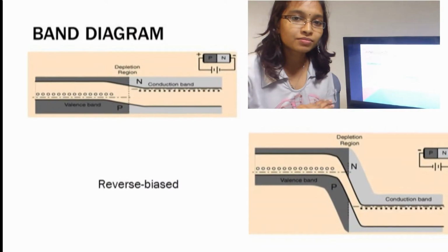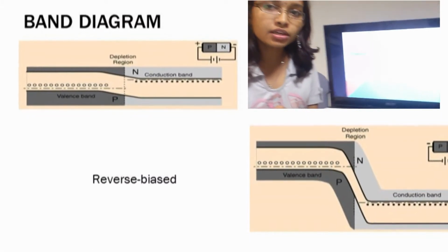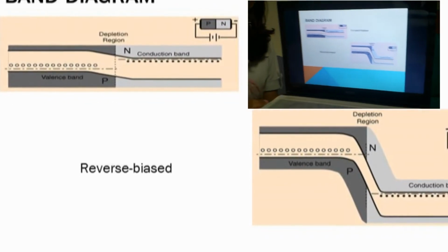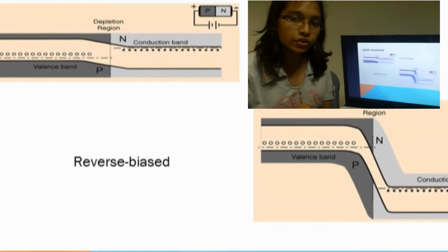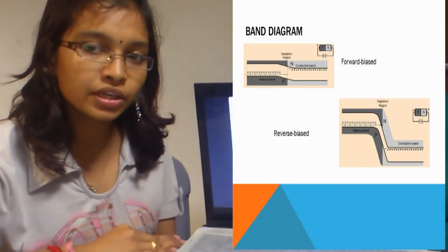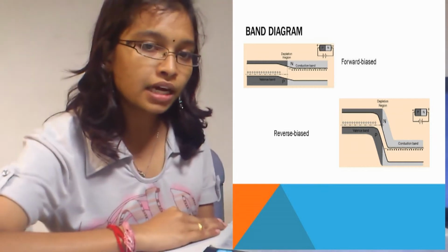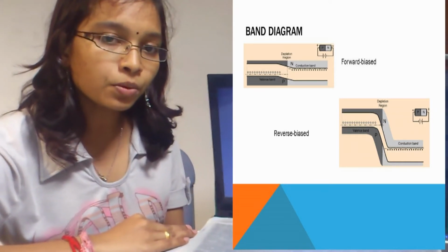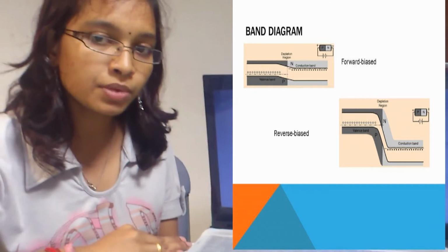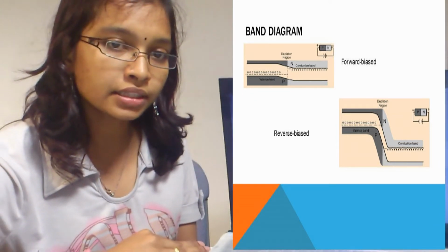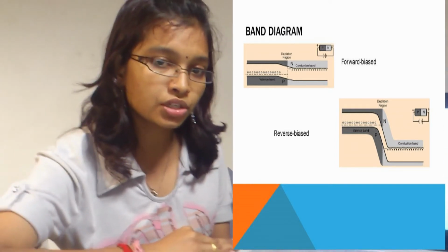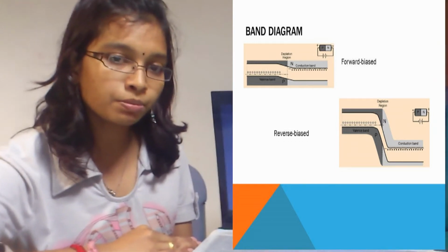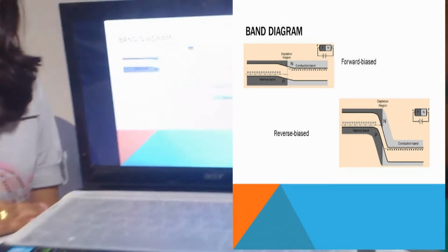To reverse bias the PN junction, the P side is made more negative, making it uphill for electrons moving across the junction. The conduction direction for electrons in figure 2 is right to left, and the upward direction represents increasing electron energy. The applied voltage is proportional to the difference between the Fermi energy in the N-type and P-type quasi-neutral regions. The total potential across a semiconductor equals the built-in potential minus the applied voltage.